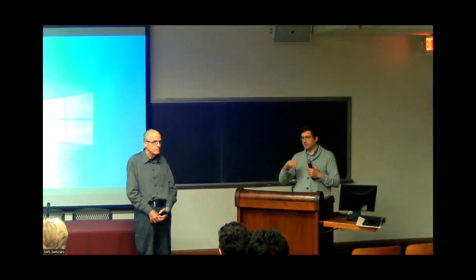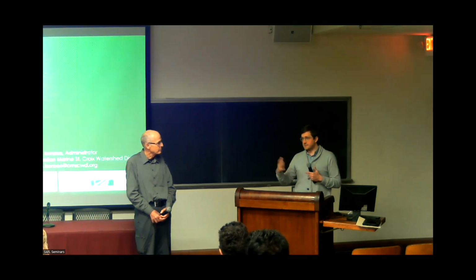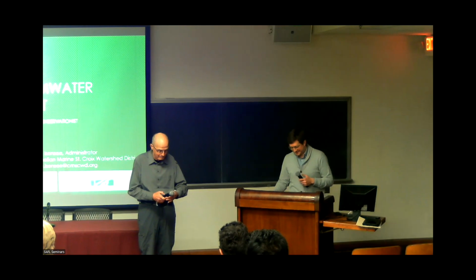So we're okay with designing them for 3 to get that 48-hour drawdown. And it's also good for the biochar and iron enhanced sand to dry out in between storm events. So hope I answered that question.